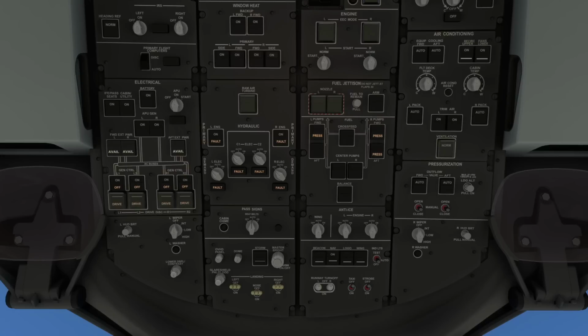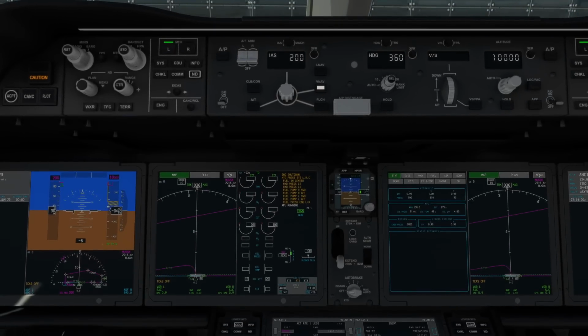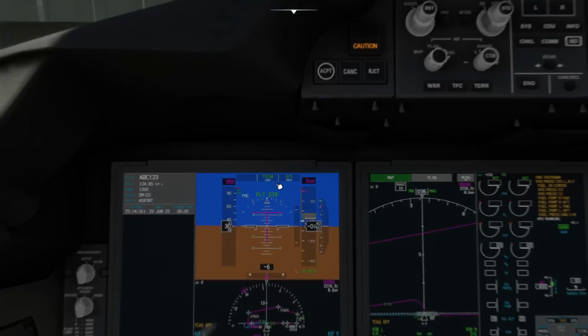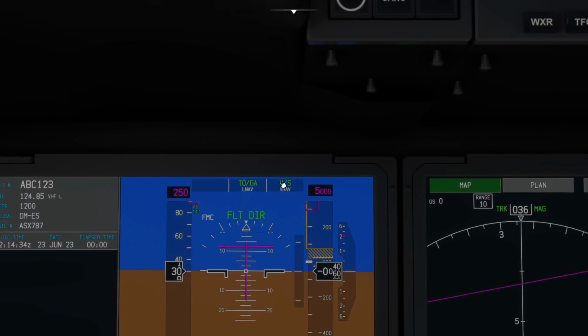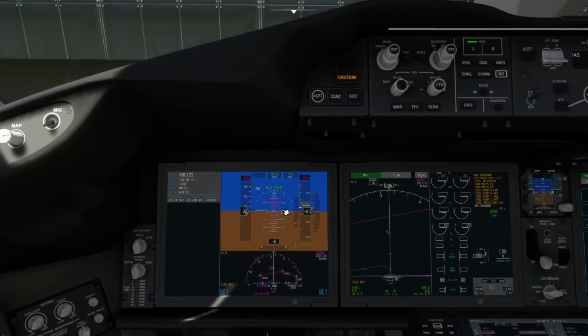Okay, so now we go back down to the master control panel for the autopilot. So control and 2 brings us here. We're going to go to 5,000 feet, so we'll pre-select that on the altitude and then press the knob to confirm it. We can turn the flight directors on now. We could select vertical speed mode to take off, or to get off the runway I should say, so 2,500 feet a minute perhaps. But we can also pre-select VNAV and LNAV. So it will follow the route and use vertical speed as well. So you can see that reflected up here. So it's actually going to go, yeah, VS and VNAV. Okay.